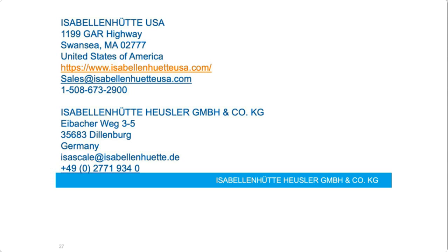Yeah, that's a very good question too. Thank you for that. The response time of our active isolation measurement system varies between 5 seconds and 30 seconds. And why is that? This is because it depends on the Y capacitance of the measured system, so the capacitance between the high side and ground. The higher the Y capacitance is, the longer the response time will be, but the maximum is 30 seconds.